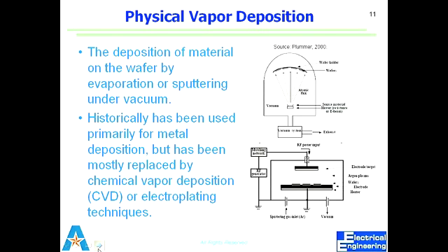If you allow the collisions to occur, they will go in all directions. So you lose much of the material. These 95% plus pure metals are not cheap. They're very expensive. So you want to do this. This pumping down is done with what are called cryo pumps. They are very, very efficient pumps. In many cases, we have to put liquid nitrogen on the pumps to keep them cool.